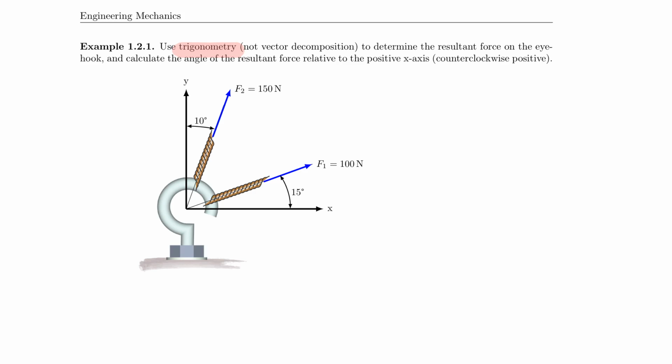So let's do that. I first will move my F1 parallel along this line, and then I will move my F2 parallel along this line here. And now the diagonal within that parallelogram is really my resultant force. So let me put that in for you. This would be the resultant force, or the visualization of it. F resultant is what I call that.